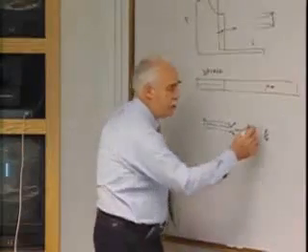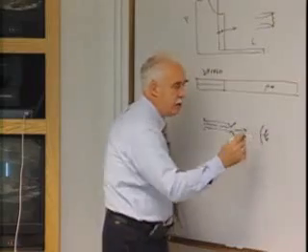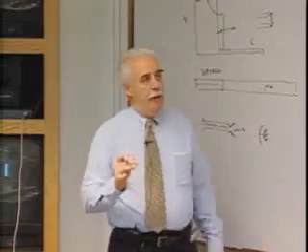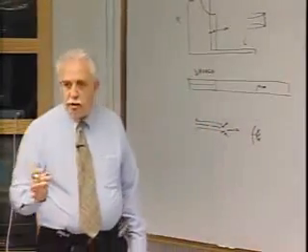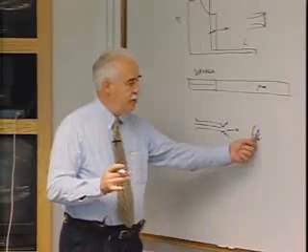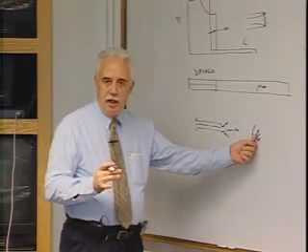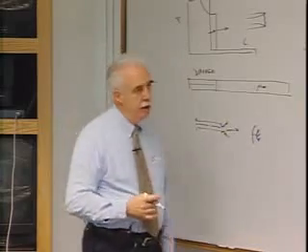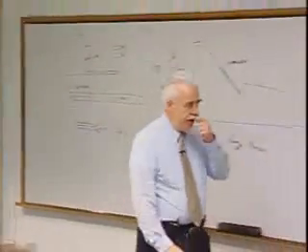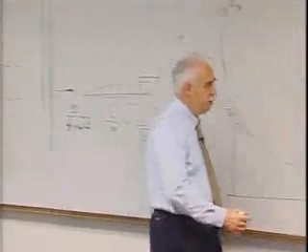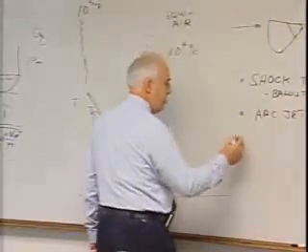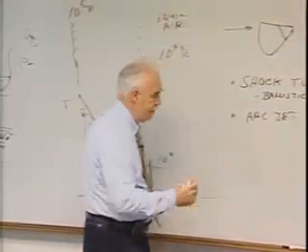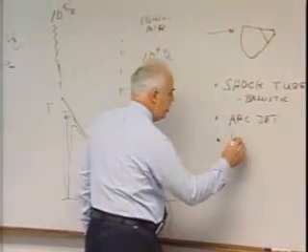But this is where we do research on ablators and research on surface catalysis, which I'll talk about in a little bit, which really can affect the heating, particularly on the shuttle. And I'll show you some results there. But in any event, the arc jet is the other major facility from a TPS material standpoint, TPS being thermal protection system. Wind tunnels are classic.